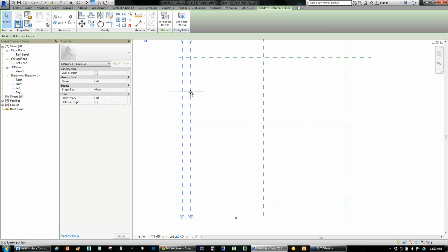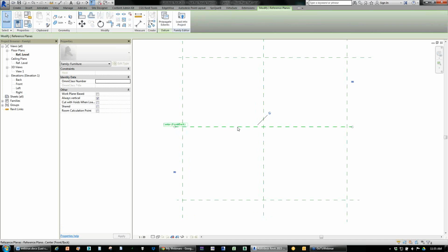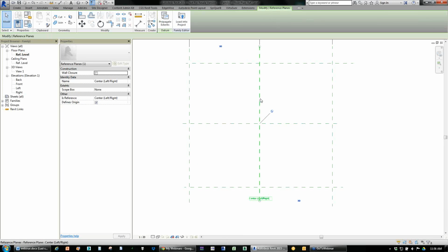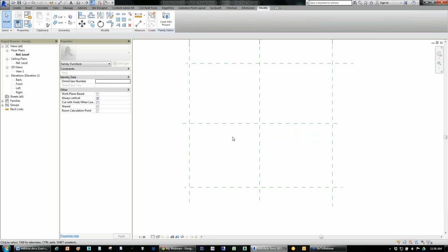Also, when I resize the object, it will resize itself around that insertion point, in the same way as an AutoCAD block, for example. If I was manufacturing an L-shaped workstation, it wouldn't make sense for me to have the insertion point in the center of it and for it to rescale around that center point, because if I had a cluster of 4 workstations and I resized them, they're going to end up spreading into each other, which is not desirable.